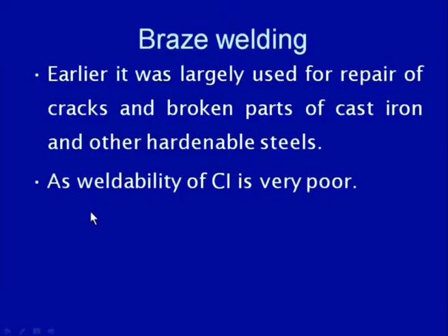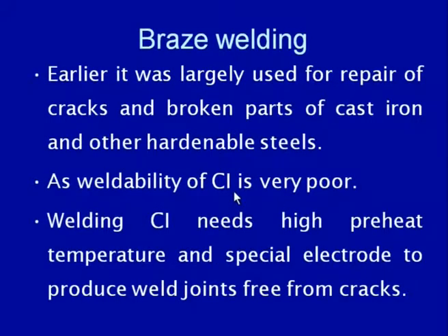braze welding has been very extensively used earlier, and this is mainly because the weldability of the cast iron is poor. If you perform welding, due to the high hardenability, this will lead to cracks very easily, and the welded component with the cracks cannot be used for any significant mechanical purpose.